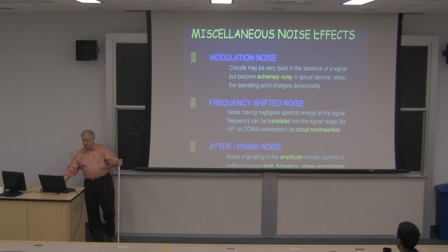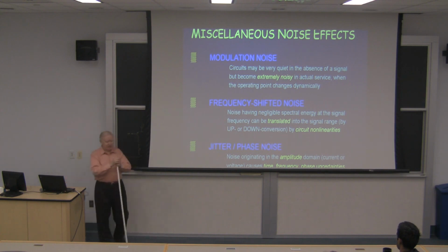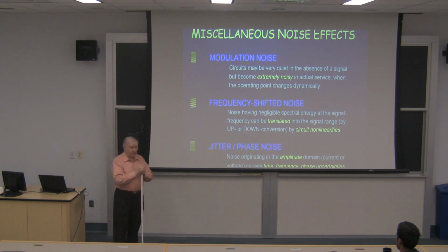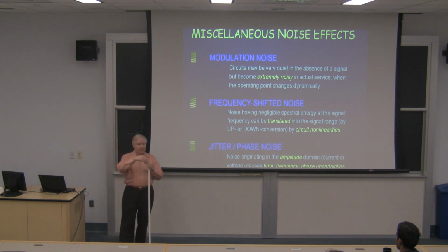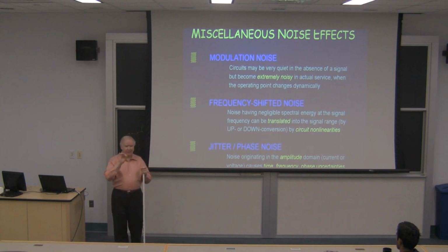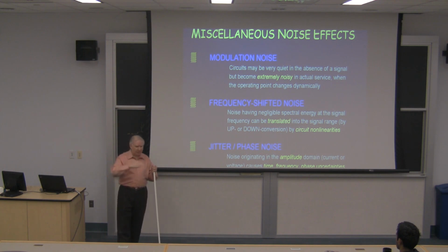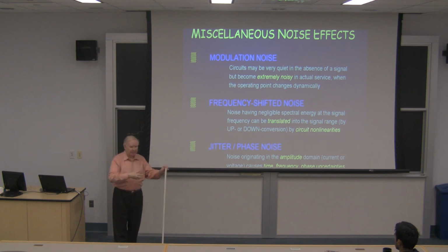Oh, yeah, let me first mention, there's another kind of noise you have to worry about, that's modulation noise. When a circuit is analyzed in SPICE, it's too easy, maybe, to stick with AC analyses. And you miss the fact that when you change the working point, as an actual waveform comes along and does its thing, the noise is going to vary.